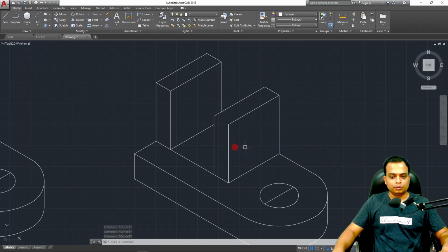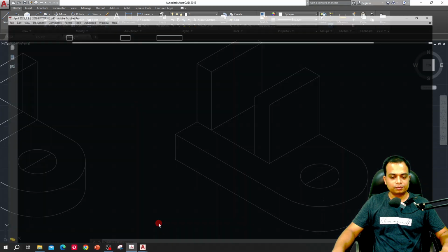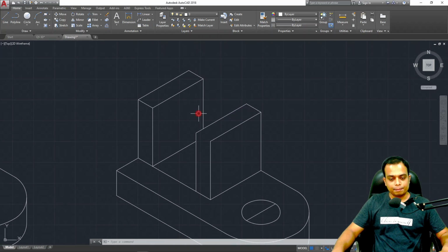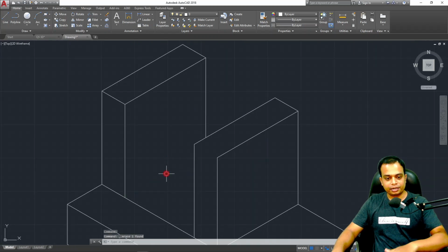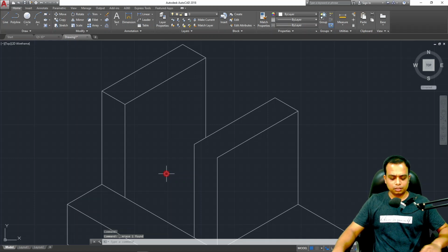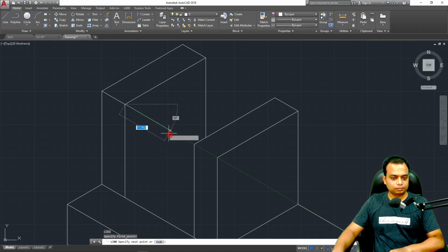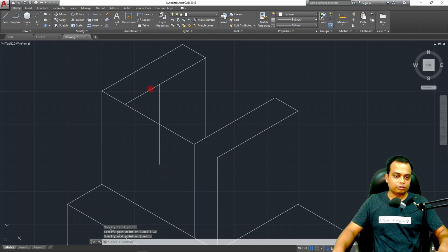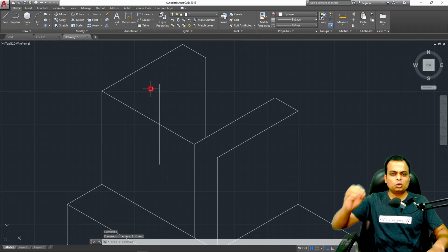Okay. Now I need to make a semicircle over here. Again, if you watch this profile, there is this semicircle which you need to create on a vertical plane, basically. How do you do that? The approach is very simple. I think we should get rid of this also for now. Join. The diameter is 30. You can see this. Take the center above 15, below 15, enter. Done. I think we should get rid of this line also, not to create any kind of confusion in your mind.